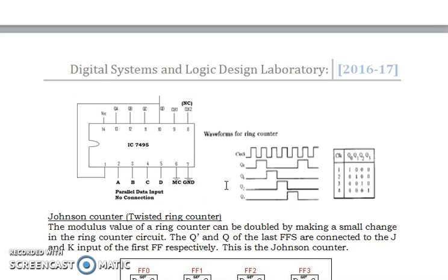How you have to perform the execution is, after finishing the connection, switch on the circuit. Then if you see the circuit, there is a connection from 10 to 1, and a connection from 10 to the output LED. Remove the connection from 10 to 1 and give it to ground. Connect to monopulse and give clock pulses until only 1 output is having a high value. The rest all should remain 0.